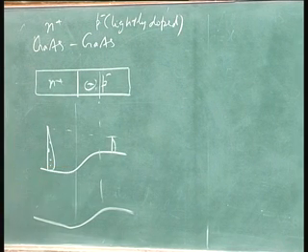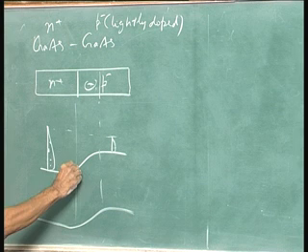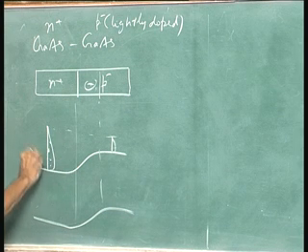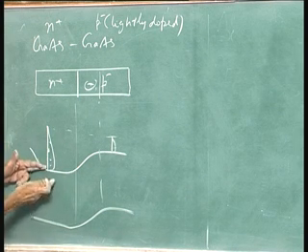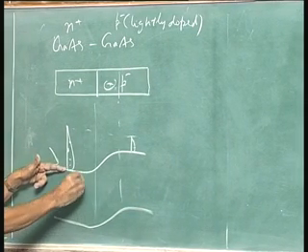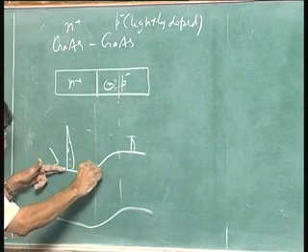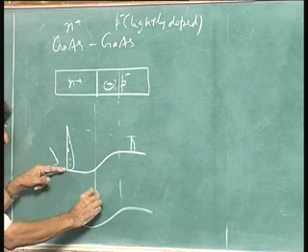So, delta E_c, the whole thing which resides in the notch, is the one which decides how many electrons are there. I will take this up again in the next lecture, but this is the point that you should note. I have just drawn only that portion, let us remove that, because that thing will go down. Thus, this is for the AlGaAs, gallium arsenide system. Okay. With that I stop today.